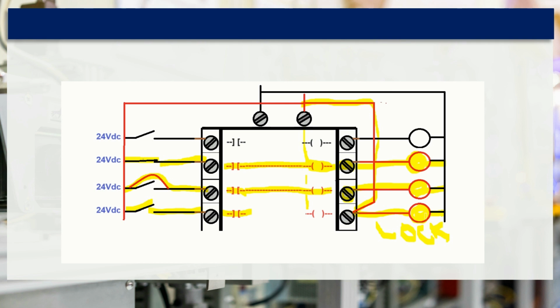There are a lot of people that I've worked with for many years who would still think if you forced on an output, it would change all the logic internally, and they would look at it and forget, and they would not see that it's on, and they're going, I don't understand what's happening, and the output's left on. The other thing that can happen is that you can force on an output, forget about it, and you look at the logic trying to figure out why your machine's not running right. Oh, the output's forced on, but that doesn't make sense. The logic's turned off, but it's been forced on. I forgot it's got the lock on it. Yeah, better take the lock off.